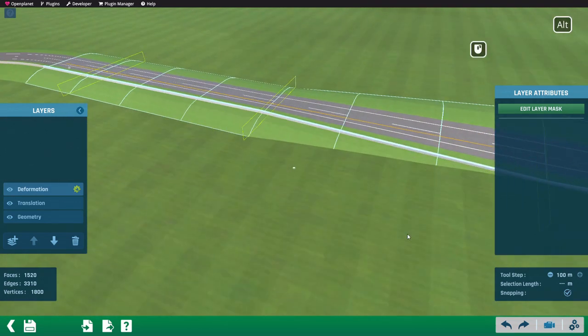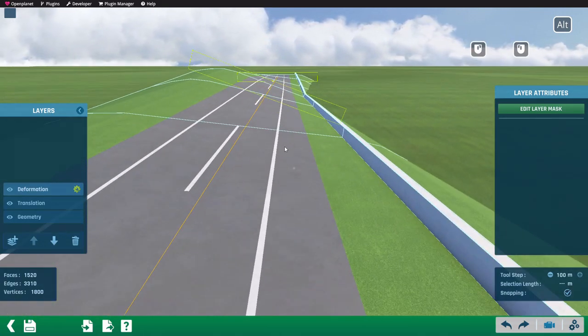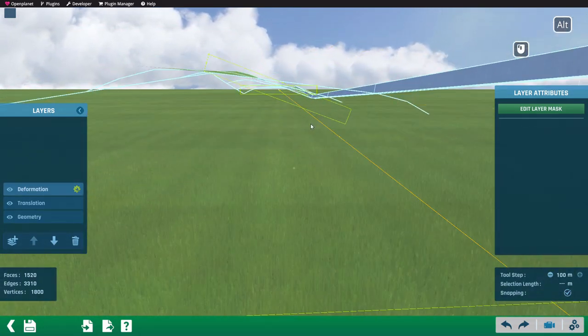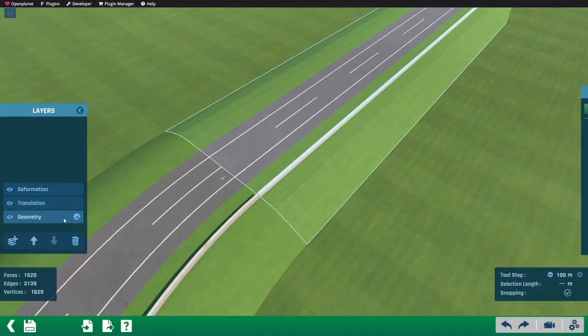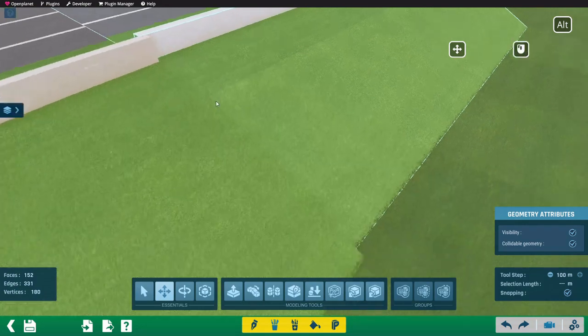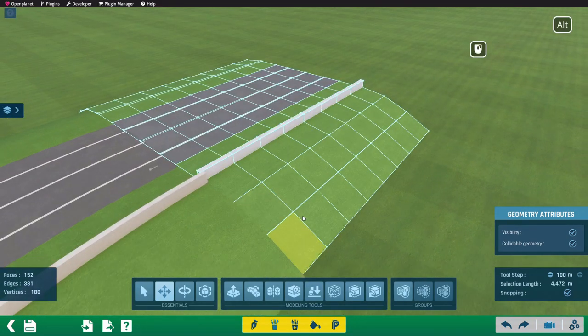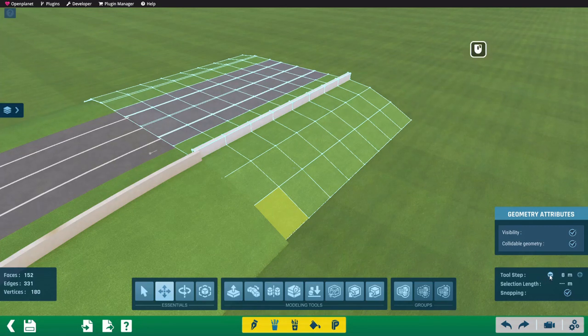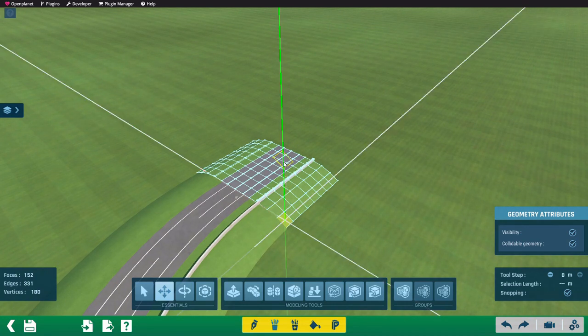The first reason has to do with the position of the pivot point of the banking rotation. It is exactly located in the calculated center of the item. The editor calculates the highest and lowest as well as the leftmost and rightmost points of the geometry and calculates the middle point of these extreme values. This often means that the pivot point of the banking is below the racing surface, but it depends on the geometry you use.